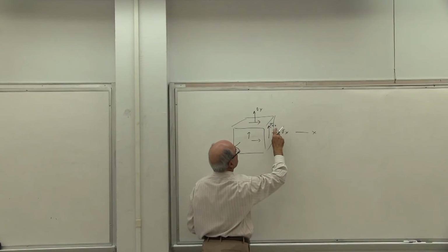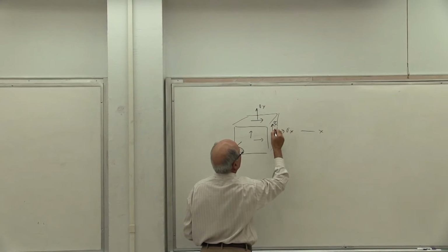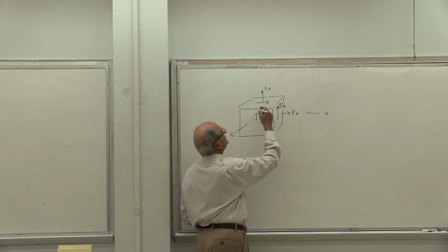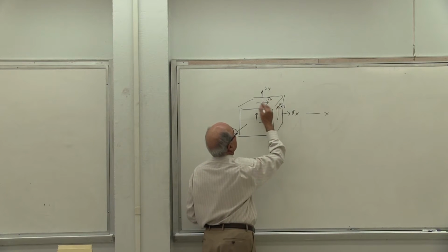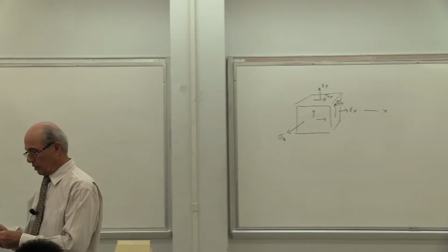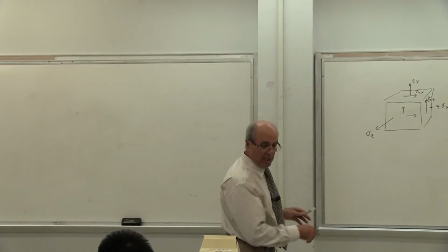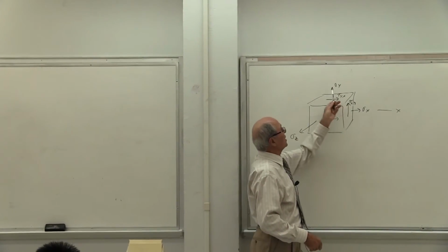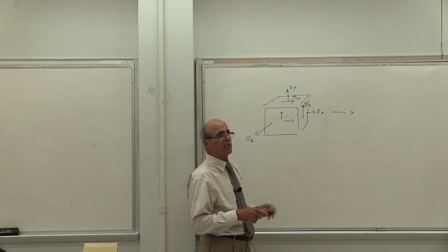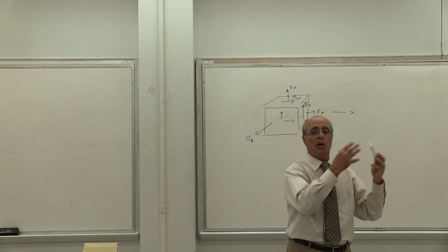Anyhow, the first term is exactly what the first term was. The second term, the only thing that's changing is all the sigmas now becoming epsilon. Then for the last term, we get gamma xy, sine theta, cosine theta. That's what we get. Which, if you look at it, there is a slight change. Do you see that? There is no 2 there. Is that correct or not? Yes? If there was a 2 there, I could use the same idea as Mr. Mohr did, turn this into a Mohr circle, but it doesn't have a 2. So what do I have to do? I have to add a 2 there. Is that correct or not?